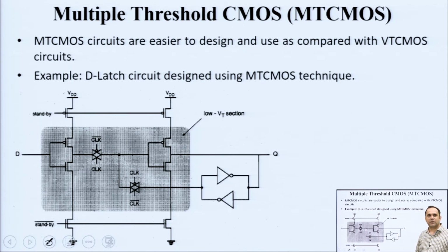In addition, you have this PMOS here connected to the standby signal, and an NMOS here, and then this is a bistable latch element. So, whatever comes out gets latched into this circuit. You can see the shaded region is a normal circuit, but you use low threshold voltage devices, and you use high threshold voltage devices for reducing leakage in standby mode.